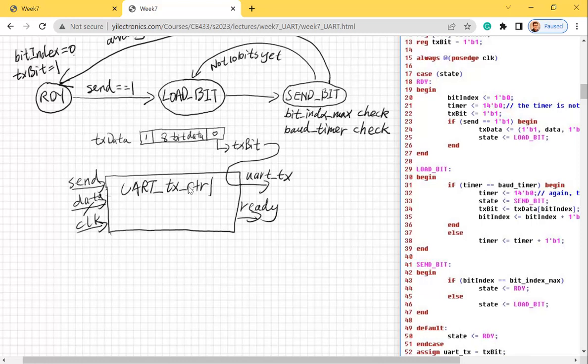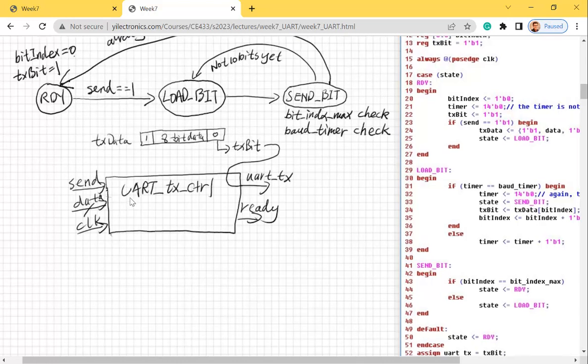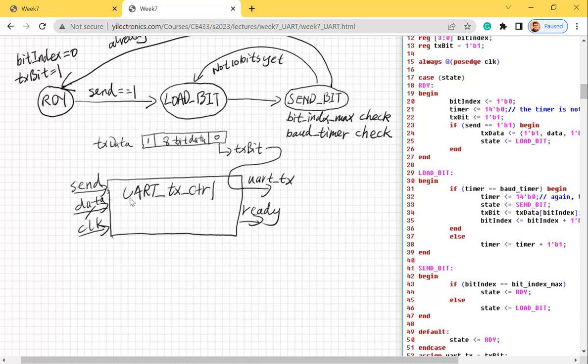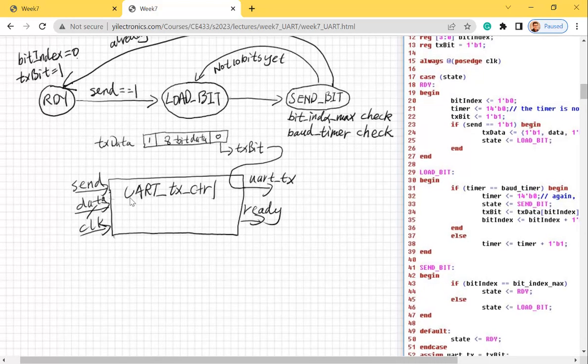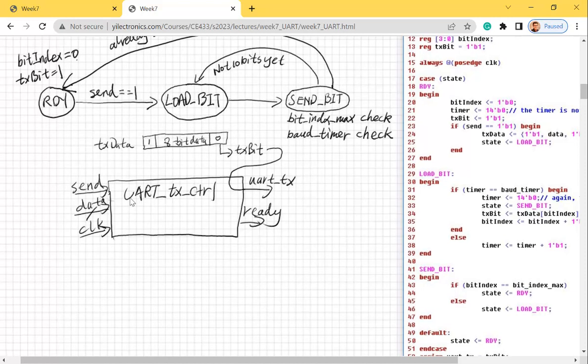Think about why we need a TX. We need a TX because we are sending a byte to the outside world, right? So where is the byte from? Where are we getting the byte? Is the TX responsible for creating that byte? No, it's from the computer, from the CPU, after the calculation, whatever. They just generate that 1 byte. So that 1 byte should be input for the UART TX module. See here, it's 8-bit data as an input to the TX.